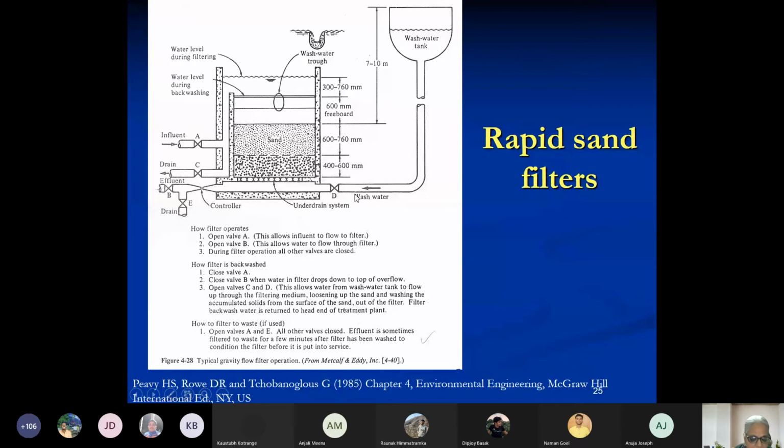Because of the high water velocity, you get complete fluidization. So this is a solid bed of sand. You can just imagine a glass with sand in it. It's a static bed. But the moment you have a jet of water, sometimes combined with air, there is no air valve shown over here, but in general, in practice, we have a high velocity jet of air and water. The two together in the upflow mode will fluidize the entire bed. This entire thing becomes a slurry.